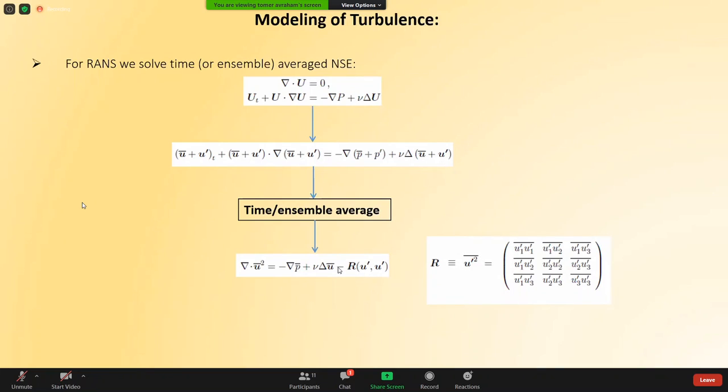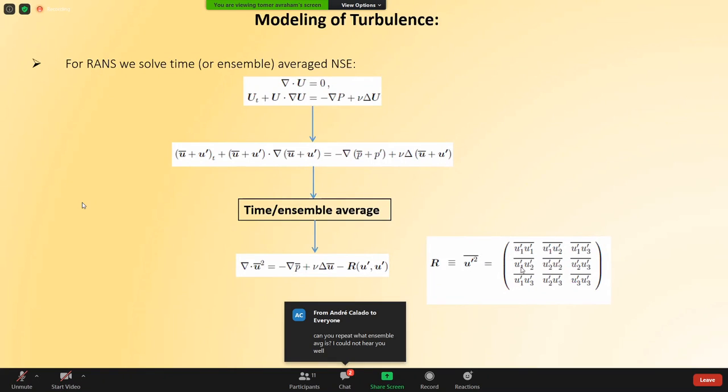What this actually means is that Reynolds-averaged Navier-Stokes equations are a little bit dissipative. They take a convective term and turn it, especially when we invoke the Boussinesq hypothesis, into a dissipative term. So this is of course a symmetric tensor.